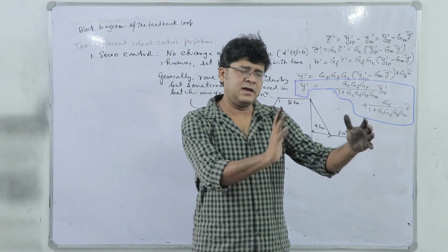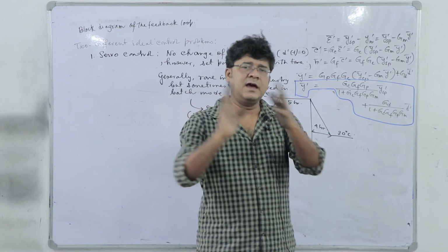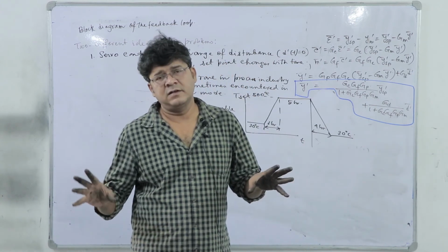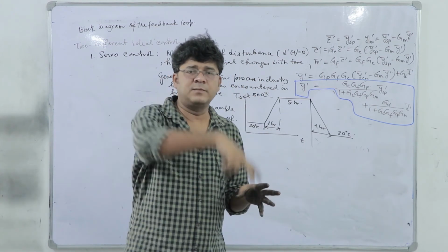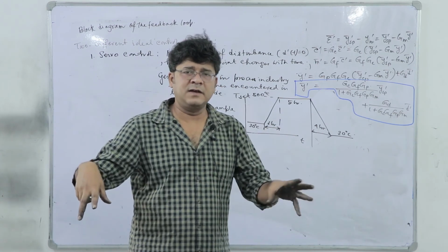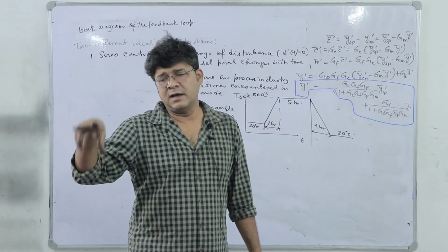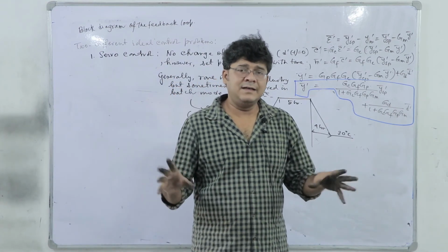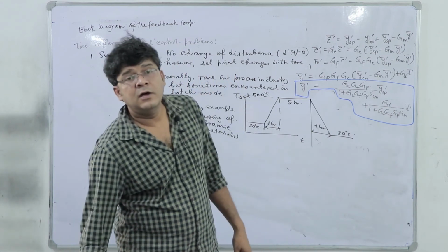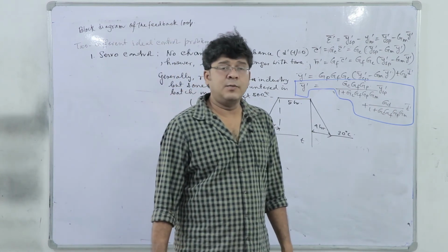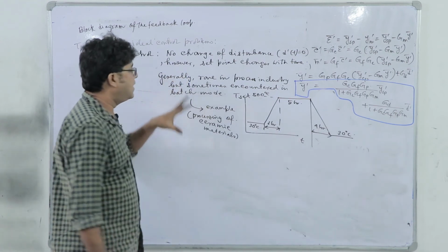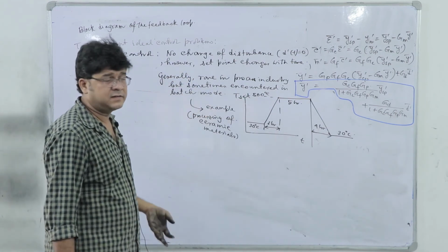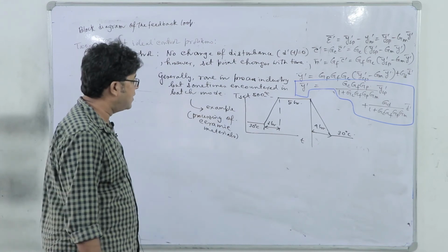So the target location and the location of the destination are all fixed. Under this condition, the robot arm is moving, picking a specific drum and keeping it at a specific position on this truck deck. That is the typical servo control which is frequently encountered in robotics. However, rare in chemical industry, but in some batch processing we need to actually implement this servo control.